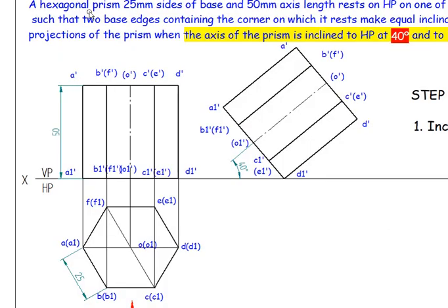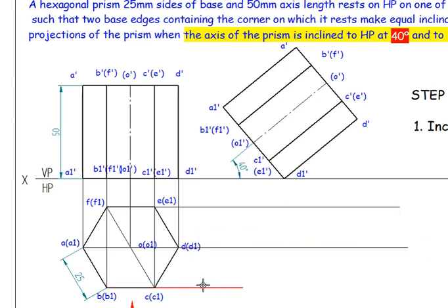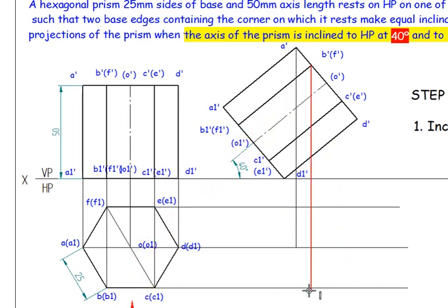So here we are going to project the lines first by horizontal projections. So project face by face, annotation by annotation. So I'm going to project the top face. This is the first letter A, so A is still this point. Then going for the point B, B point is here, so projecting till here. C point is still here. D point is still this point. So I'm just removing all those extra points.